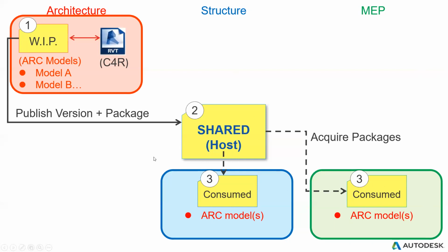in this folder. So if the structural team just changes the architectural model here in their own consume folder, it will not affect the architectural team's work in progress model. However, it would also classify the version of the model. So I think this is a very good workflow for the PM, project manager, to manage the workflow or collaboration between different teams in a mega project.